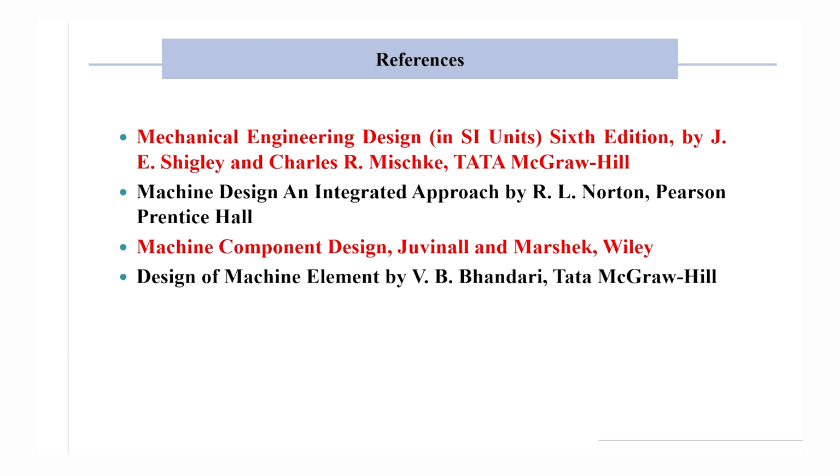Based on that, first we selected the axial pitch and thereafter we found the different factors of the allowable tangential load on the gear and the tangential load which is acting on the gear, considering the power output H0 which was given in the problem and taking consideration of the efficiency of the drive when the worm was driving and the factor of safety and the application factor.